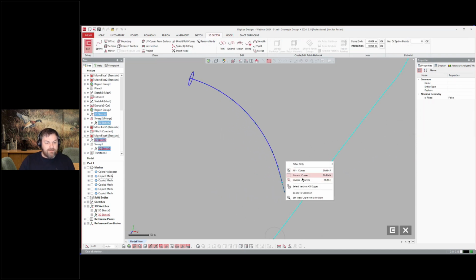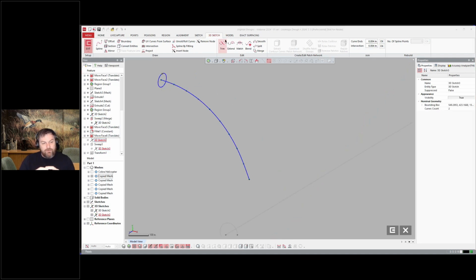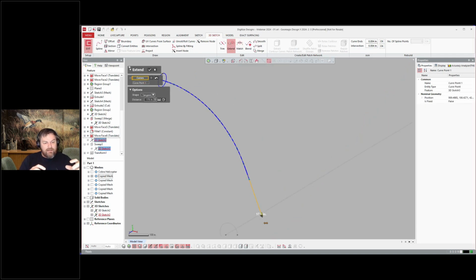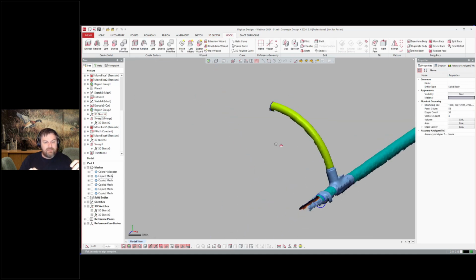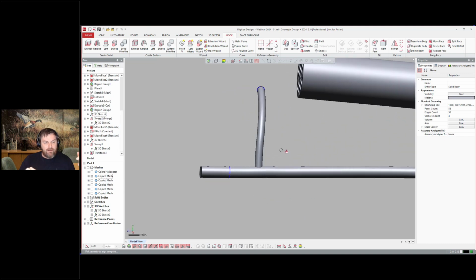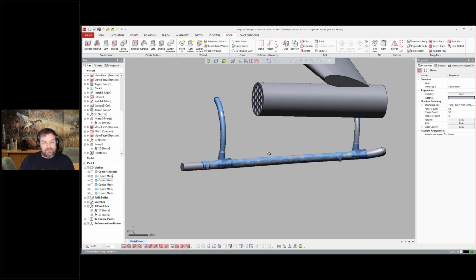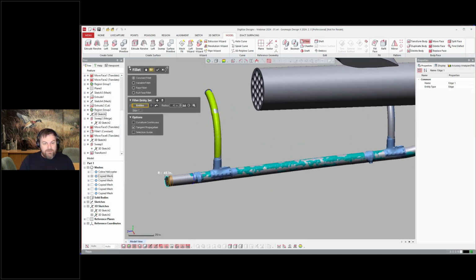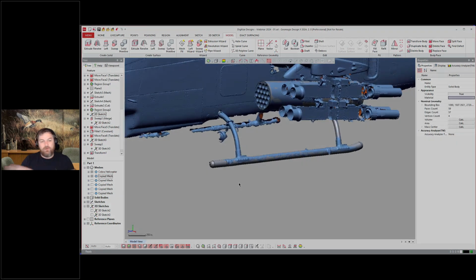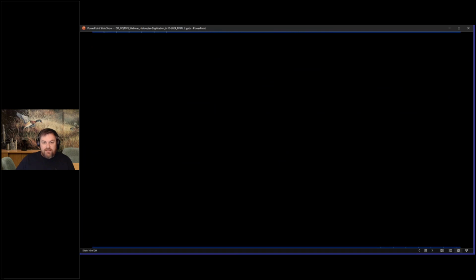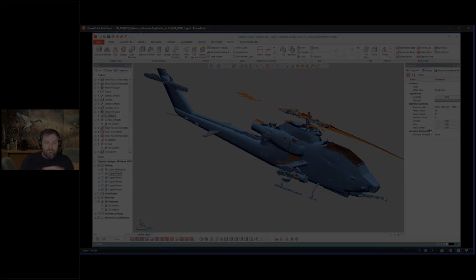If I wanted to, in this instance, I only modeled it and there was a coupling between the two. I'm basically saying, let's extend that curve out, and then once I extend it, let's set those as coincident. And you see that the CAD model updates, and even the other instance of the leg updates and intersects with the landing gear. Now, there's a whole host of ways of modeling these things. This is just the approach that I took to model it.